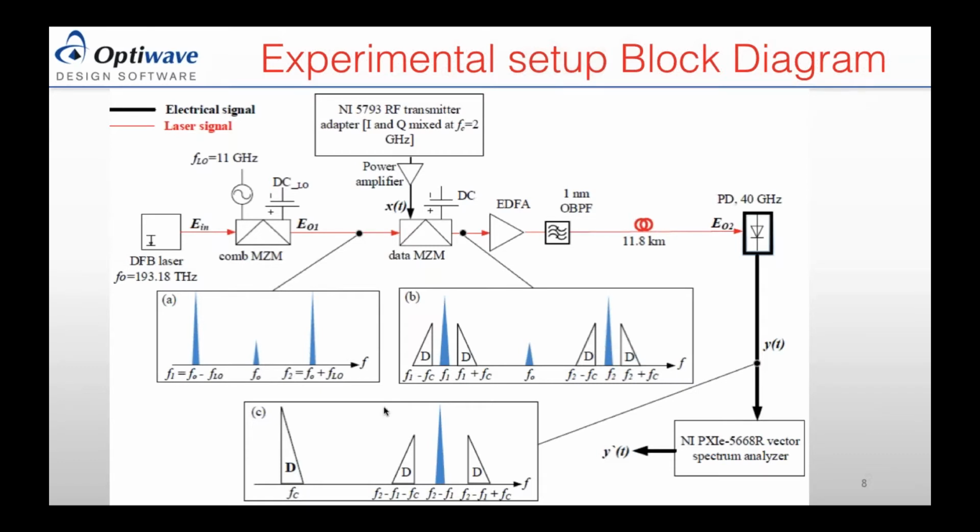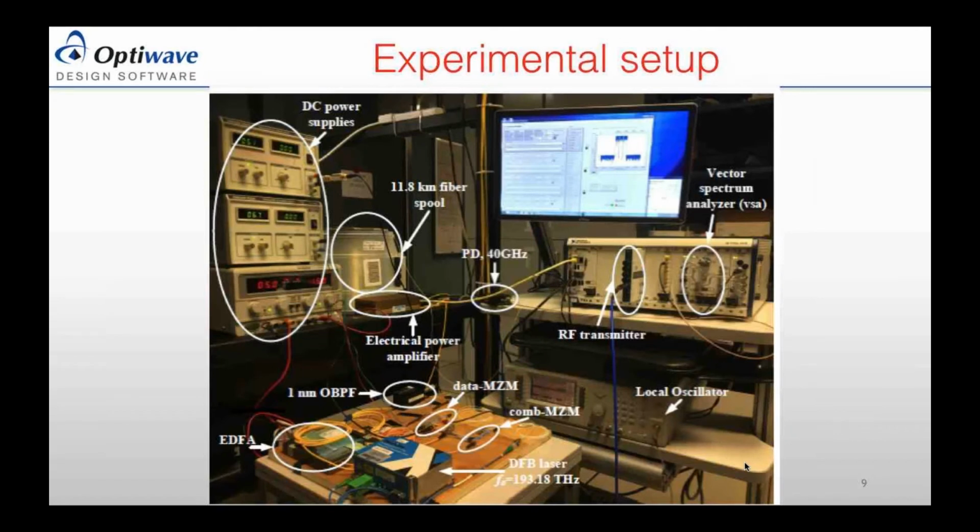So we have almost 4 contributions, and then we have 2 contributions at this frequency, from beating the blue one with the one that's closer to it there, and this one with this. So we have a similar contribution right here. Then this blue one is a result of beating F1 with F2. This can be seen at the output. If you have full span, you will be able to see all of these tones and data with the spectrum analyzer, as well as with OptiSystem.